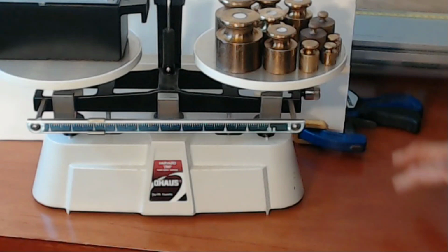These are calibrated sets. They are precise within 0.1%. So we can, instead of trying to figure out all of the uncertainties of each of these individual masses, just look at this mass, the mass we read here, and calculate the uncertainty at 0.1%. So I'm going to show you that in a second. Why am I doing that for the maximum mass that I can use here? Because in the end, that's going to be the uncertainty we want to use. Okay, let me get a piece of paper and show you the next step.